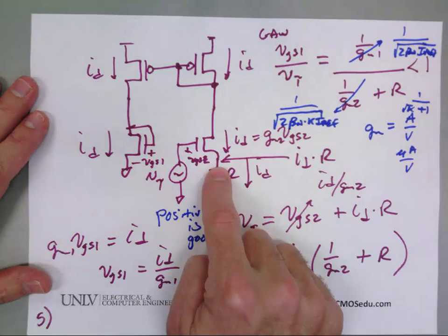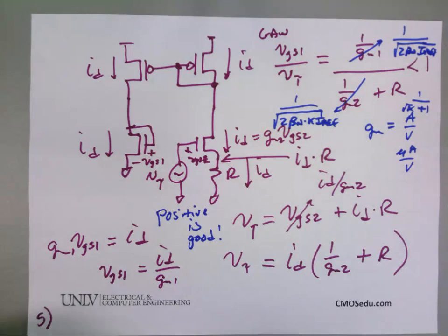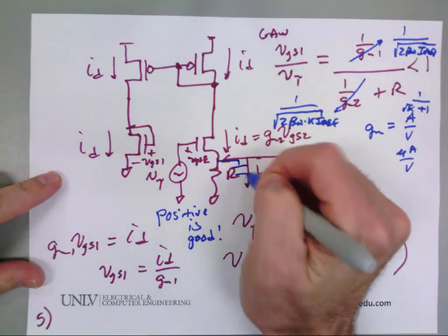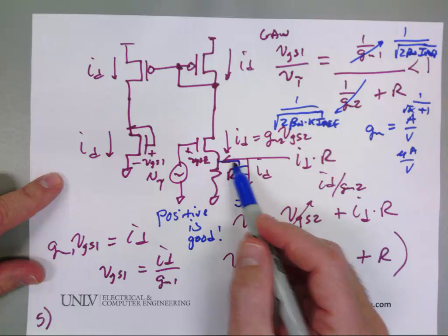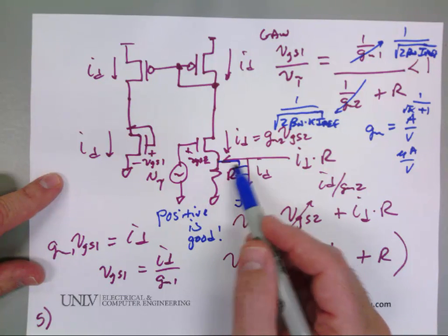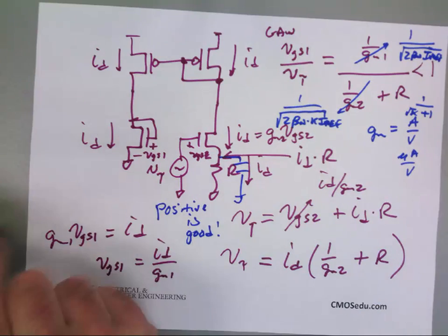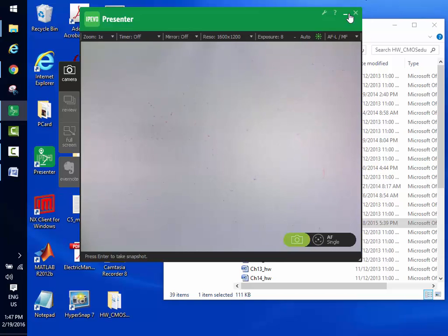So they take this resistor and put it so that it goes off chip. Well, if you put it off chip, it's got a big parasitic capacitance from the bonding pad and everything that shunts it. So if you put a big capacitor across there, it can cause the circuit to become unstable. That's really easy to show in simulation, so I wanted to show you, okay? Because you're making sure that the gain at some frequencies becomes very close to 1. So let's go look at figure 2024.